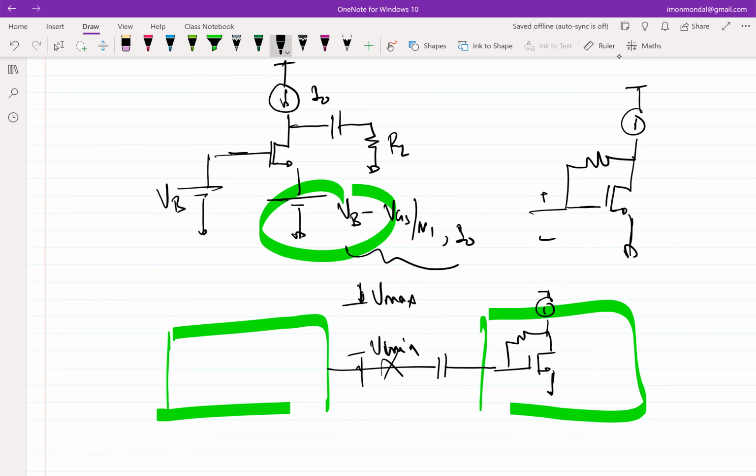So you will probably not be able to use AC coupling capacitors everywhere. Maybe when you are coupling a signal from outside the chip to inside, you can have specific ceramic capacitors sitting outside the chip on the board, like on a big PCB, then it's fine. But you cannot use half of your chip just to put a coupling capacitor.